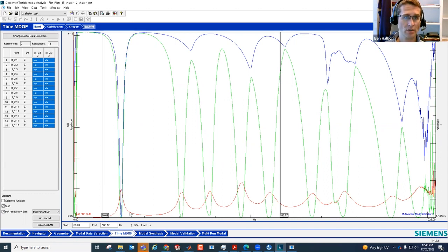And in this case, you can see, and this is discussed in the tutorial, that at this frequency here, the mode indicator function drops twice. That indicates that there are 2 different resonant frequencies at that particular area, and it will become clear as to why we need 2 shakers for this kind of structure when we subsequently interrogate the shapes and the results from the analysis.